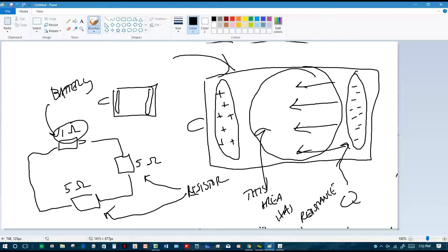And then what I would even tell you is that the cables that we've used to connect all these, do those have 0 resistance? Do the cables themselves that we're showing here, do those cables have 0 resistance? No, everything has some resistance. You might find out that this cable has 0.5 ohm of resistance, that this cable has 0.5 ohm, and the cable over here has 0.5 ohm. So in the real world, electrical engineers and electricians all have to consider this. What would really, in my new picture, be the total resistance of this circuit?